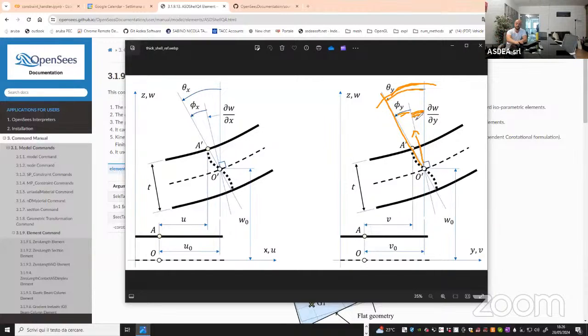So this rigid rotation is actually a derivative of a linear function, so it has a constant feature, okay? So basically you are computing a shear deformation from a linear function and a constant function, while this deformation should be constant. So when it comes to the finite element formulation, there are cases in which this deformation cannot go to zero. Okay, so there have been many ways to try to avoid it, but the first good attempt was done by Professor Bathe.